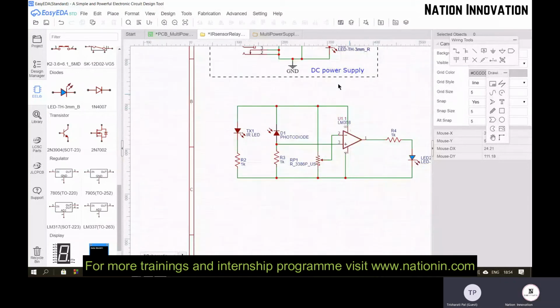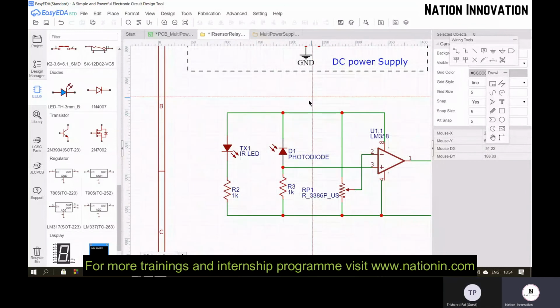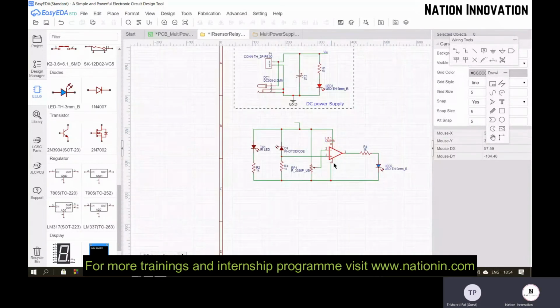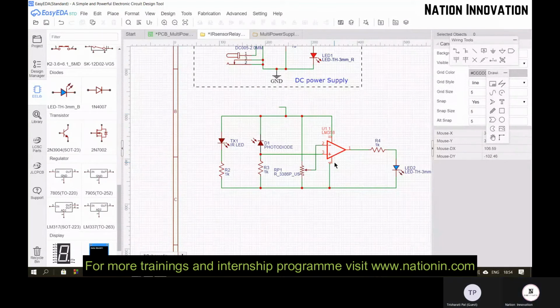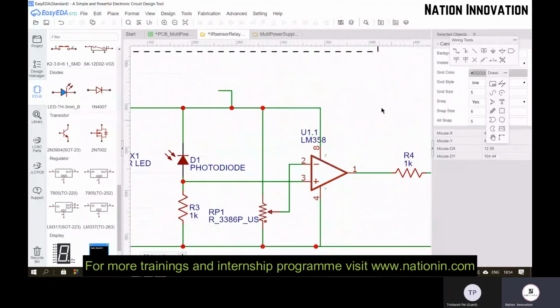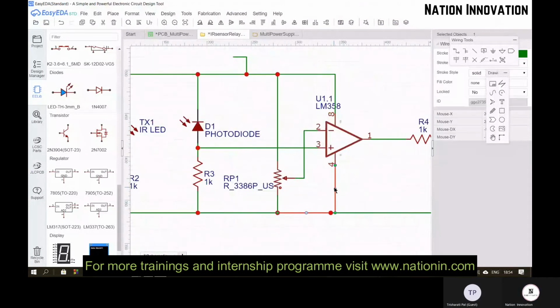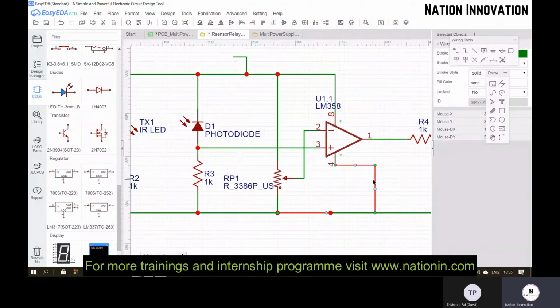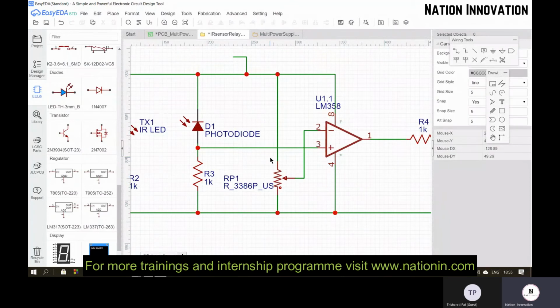So these are the connections. So this input is given by my DC power supply. Ma'am, the fourth pin is not connected. Okay, thanks for reminding. If you get confused whether the connection is done properly or not, you can drag that component and see whether the connection is moving or not. If it is not moving, then you need to do a proper connection again.